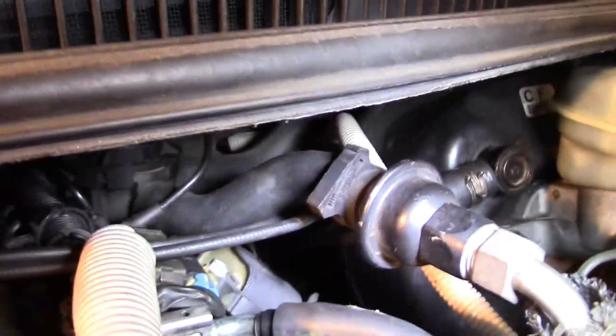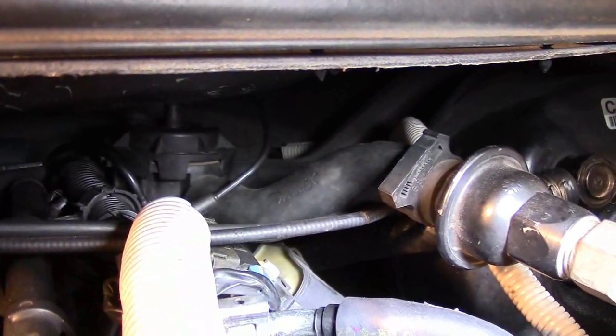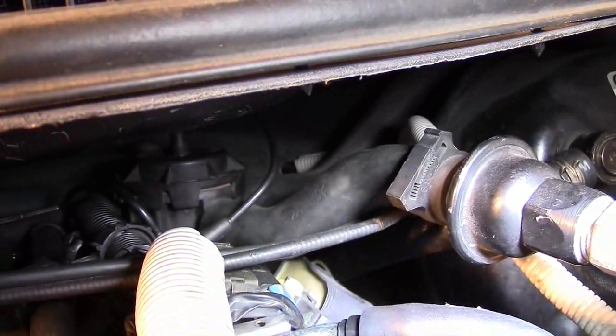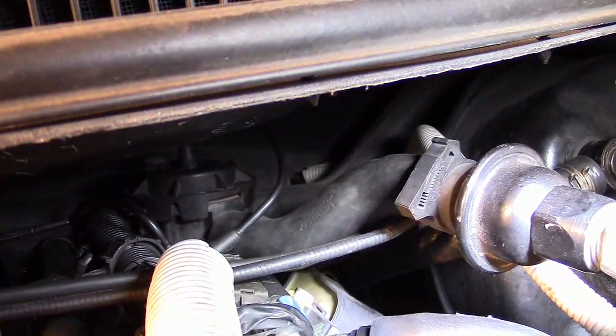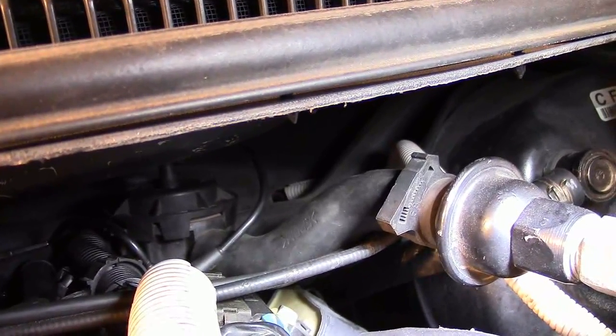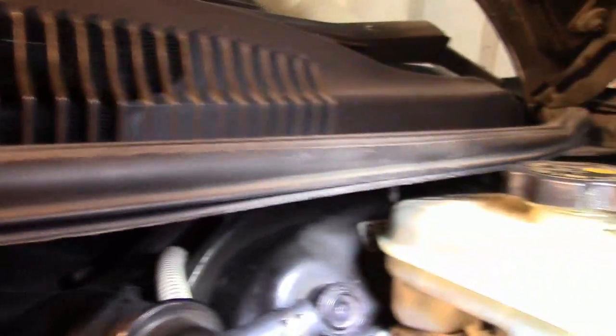Now, if we look at our diverter valve, there is, just like on our diagram, a third hose. Where do you think that has to go to? Of course, it has to go to the air pump. So now we'll be able to find our air pump without consulting a diagram or some Haynes manual jockey on Yahoo. So let's follow that.